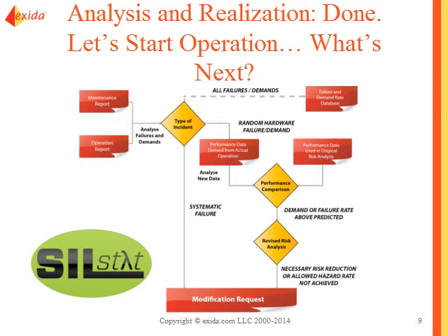So what the standard requires is that periodically we compare the actual performance with the assumed performance. And if we conclude that our actual performance is better, failure rates are lower, demands happen not as frequently, then obviously our design is adequate. We're protecting, or maybe providing even more safety than we really need.